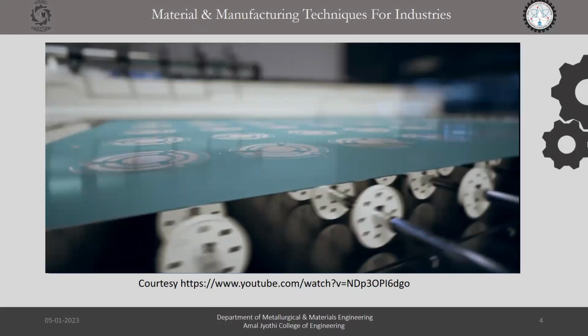The final and last step is demasking. The demasking process is peeling off the masking after the etching is done. Once the masking is removed, the workpiece is cleaned again, and any leftover etchant is washed away with pressurized cold water. Now on to the next slide.